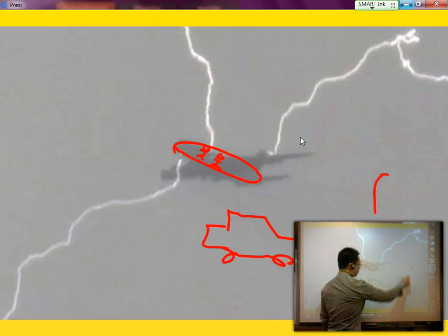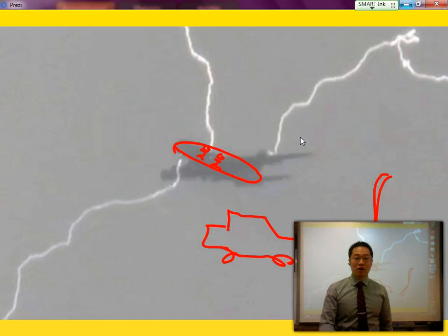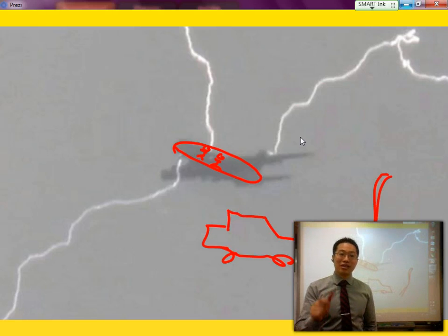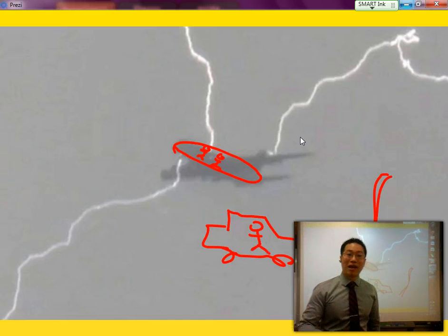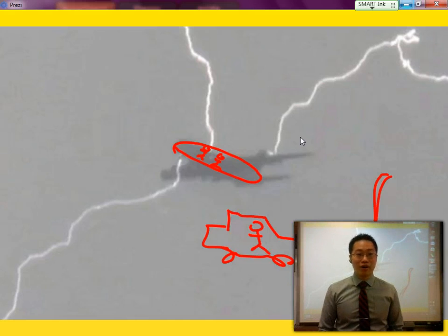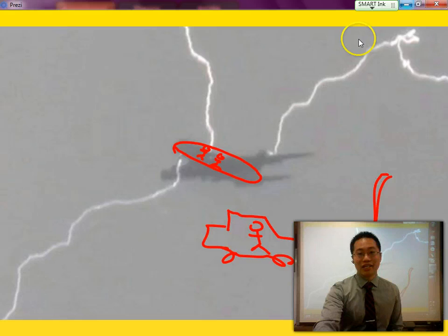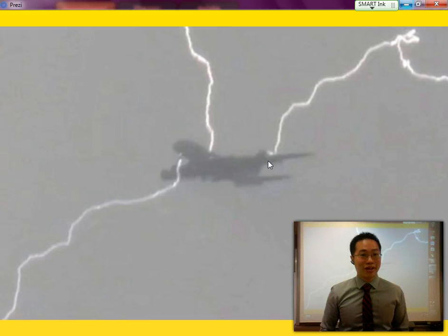And let's say there's a downed electrical line, right? If an electrical pole falls over onto your car, as long as you are inside the car, you're perfectly safe. It has nothing to do with the fact that your tires are made out of rubber, because rubber honestly will conduct electricity when there's enough voltage applied to it. But because your car is a hollow conductor, as long as you stay inside the car, you're perfectly safe. But if you step outside the car where there's a live electrical wire, then you get zapped. So just keep that in mind. If you are in some sort of high danger area with electrical lines falling, always stay inside your Faraday cage or your car.